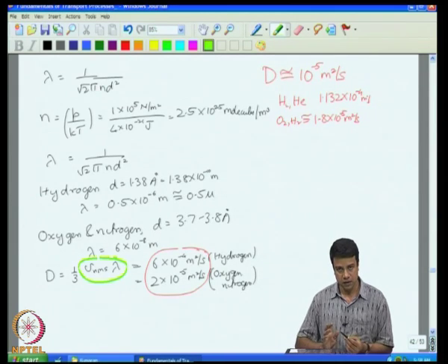In liquids, these transport processes occur due to different mechanisms. In the case of liquid metals, there is very fast thermal conduction, but momentum transport is not as fast. Mass diffusion in liquids is typically much slower than either momentum or thermal diffusion.